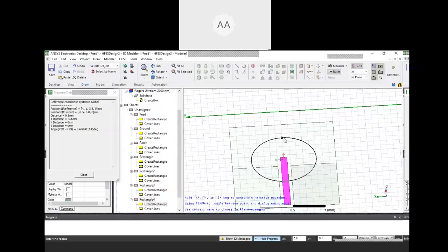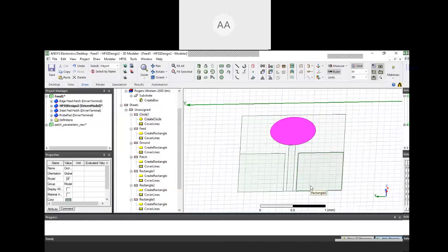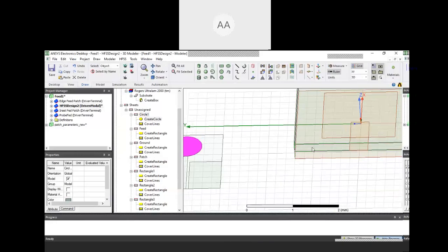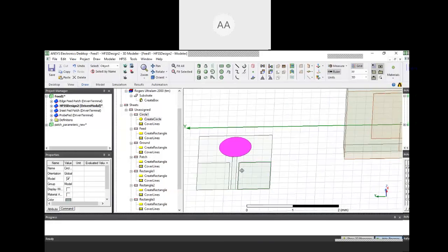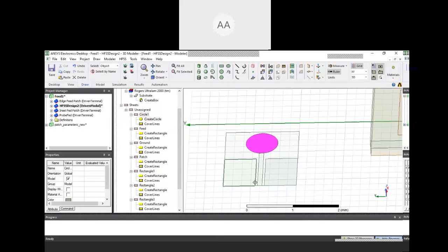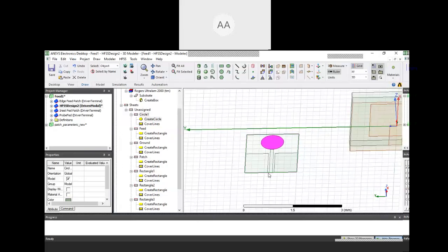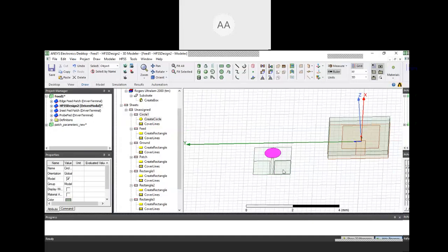If you are going for any kind of ultra wideband or super wideband design, 90% of the time you have to go for this. And second thing is, in this coplanar waveguide structure, in the other two cases the permittivity of the substrate varies quite highly with frequency, but in this case the permittivity is assumed to be constant over a range of frequencies. If you're going from, let's say, 4.4, it will remain constant over a range of frequencies, from 2 to 10 gigahertz or 15 gigahertz. So for wideband, super wideband, or ultra wideband, you generally have to go for coplanar waveguide structure.